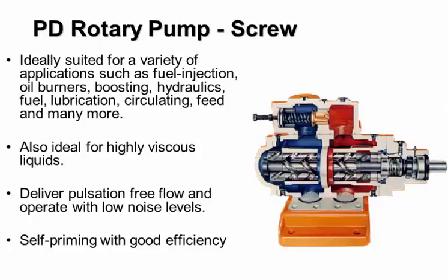And then we've got the screw pump. In this case, we've got a spindle. That's the driver, and we've got two driven spindles here. And you can see there's a spiral cut in the spindle there. So again, we're using this principle of feeding the liquid at low pressure, increasing the pressure and discharging.